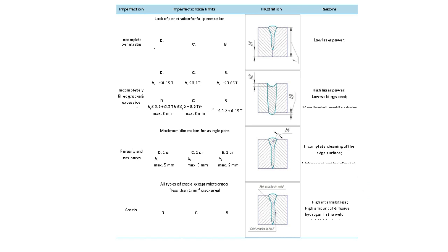In addition to these defects, it is important to mention the effect of the specific thermal cycle of thick section high power laser welding. This thermal cycle provides an extremely high cooling rate, which causes, in the case of welding structural steels, hardening of the material in the heat affected zone. Around the fusion zone, where the cooling rate is highest, a large increase in hardness is found.